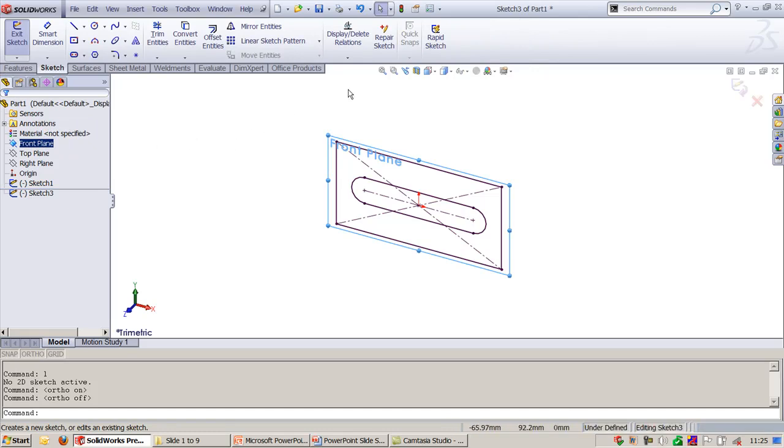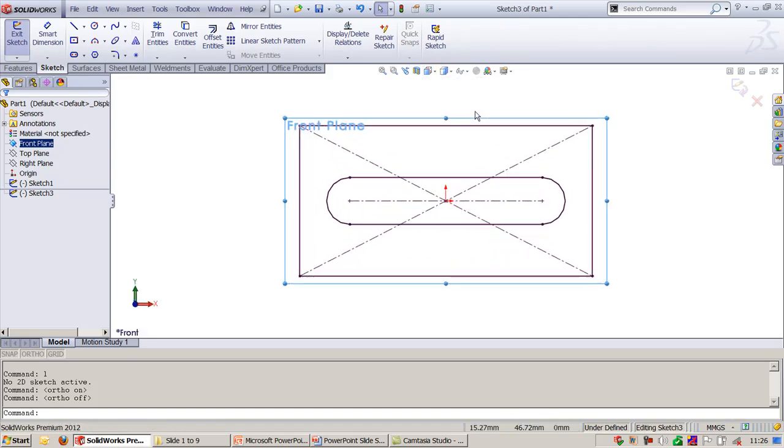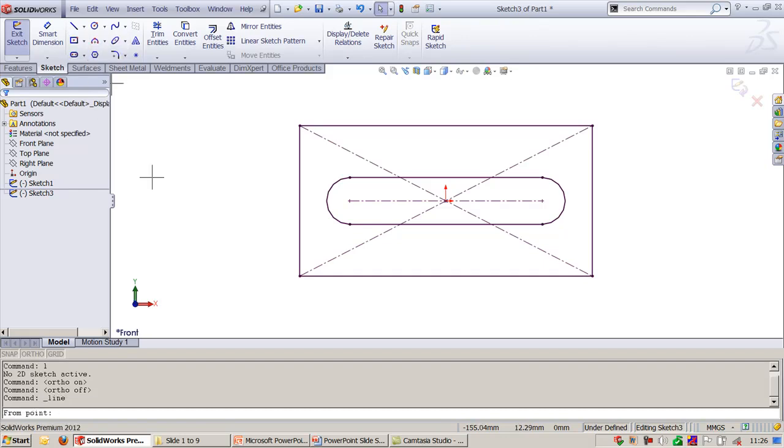After this, I'll go to one more flyout toolbar. Here I will use normal to view. And once you do this, you need to go to any one of the commands from this command manager, and I will select this line and you can draw it. This is by choosing the icon, or if I want to follow the AutoCAD methodology of typing the command here, I can say L, enter, and from point, where you don't want to use the cursor once again, I can type 0,0 and enter. Now the first point is generated, and then at 100,0 you can see the second line is generated.